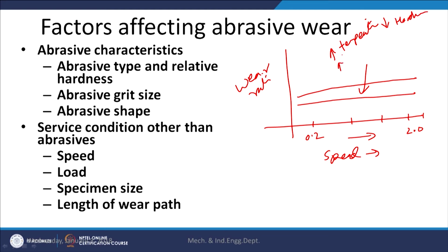And the second factor, which acts in the opposite way, is that the increase in speed leads to an increased strain rate experienced by the material during the interaction of the abrasive particles with the surface material. This causes an increase in the hardness of the material. So, these two factors may neutralize, which is why we do not generally find a significant change in the wear rate with the increase of the speed.